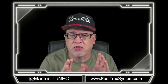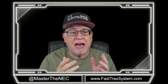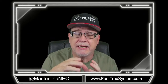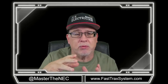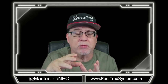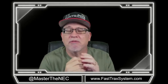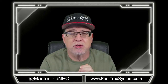Then there's also part 2, and in part 2, we focused on sizing the grounded conductor to the service, and we focused on a single raceway and how you might size the grounded conductor in a single raceway. We included things like wireways into that, so you could have multiple sets all in a single raceway, and you would have a single grounded conductor and how you would size that, remembering that that grounded conductor is also providing fault current back to the source.